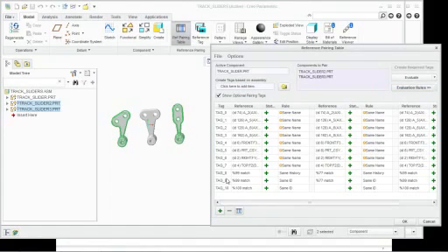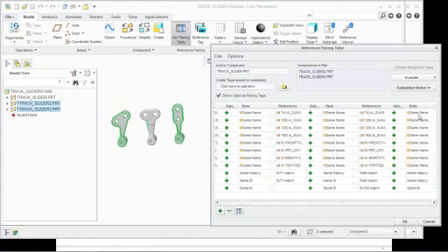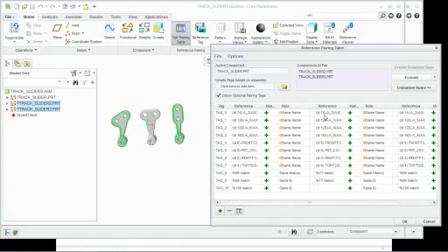So this creates the same tags just like we did a moment ago in our replace unrelated component function. Notice it automatically went in and created a lot of these. You can see I've got my 3 components here, and these were all created as variations of the same part. So using the same name, it automatically knew that this axis A2 is the same on all 3 parts.